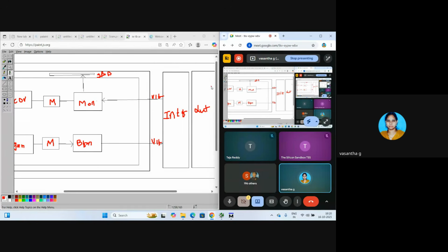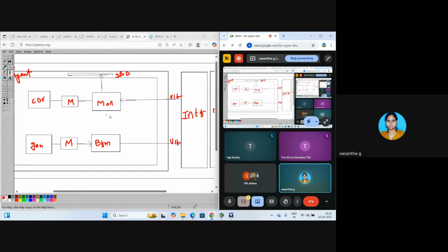I can't do direct communication here. That is the reason we require the interface. And interface is doing the bundling of signals. Whatever the BFM is driving, getting from the generator, it is driving to the DUT to check it. So when it is driving to the DUT, all the signals, it is grouping together and passing to the DUT. And again, my monitor is getting from the DUT. Here we are getting the signal level transactions and it is converting into the object level transactions because these are dynamic in nature. Again, it is taking and putting inside the mailbox.